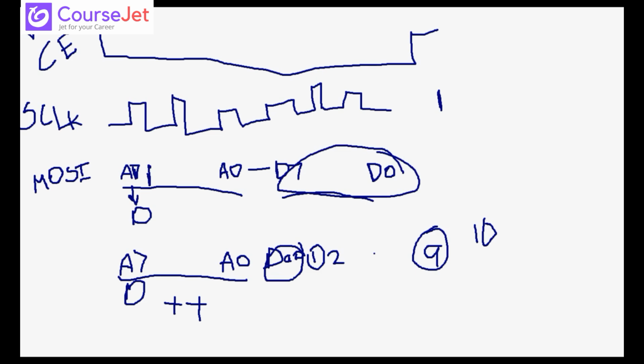So here, two things you have. First, a 0 bit, and then whatever location is there. Here we are sending data, so your master is output. If you have master input, then on the second line, which is MISO, master in slave out, you will be sending only the address from master to slave.